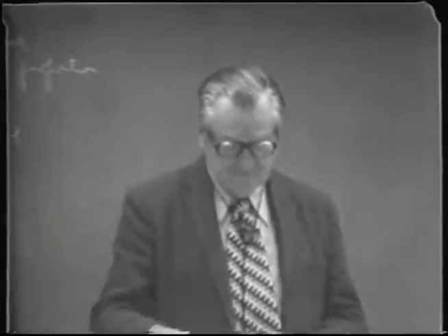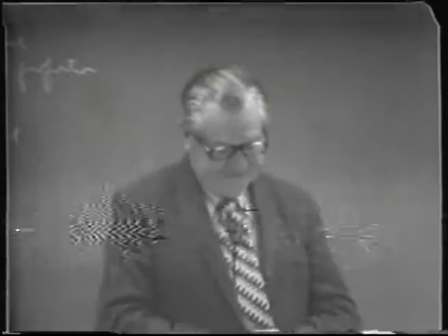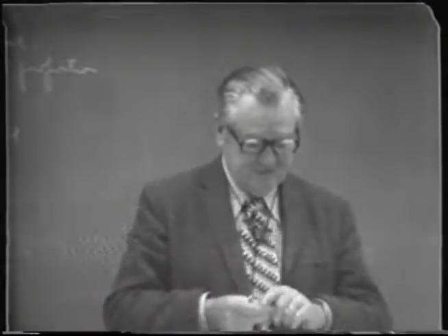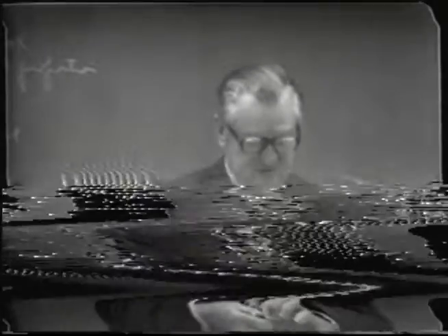And so the third chart on this handout is a little plot of the volatility of certain alcohols. Volatility is a term we simply use for the concentration in the vapor phase divided by the concentration in the liquid phase under equilibrium conditions, represented here by y over x using our symbols.